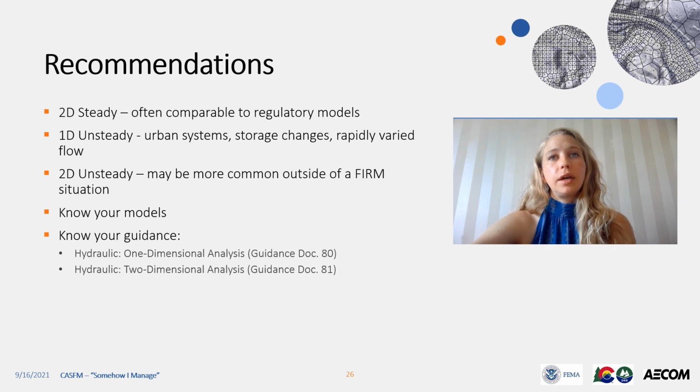Specifically for our floodplain administrators and communities, I suggest that you know your models to the best of your ability. Similar to the example I just gave, if you're handed a 2D model that's calculating water surface elevations that are much lower than your regulatory model, maybe that should shoot up some red flags.